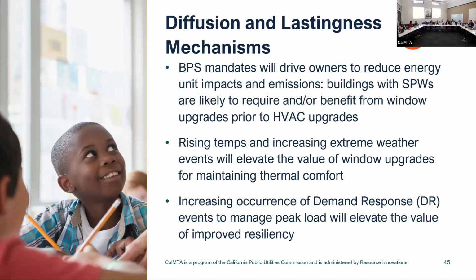Leaky building envelopes are going to be an impediment to effective demand response programs, or could reduce the impact of those programs because the buildings can coast for a lower period of time through those events. Yeah, along those lines, it occurs to me that you could actually, if it was effective enough, do permanent load shifting, where you get some load off the peak.